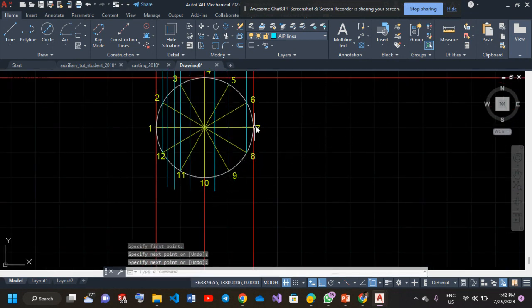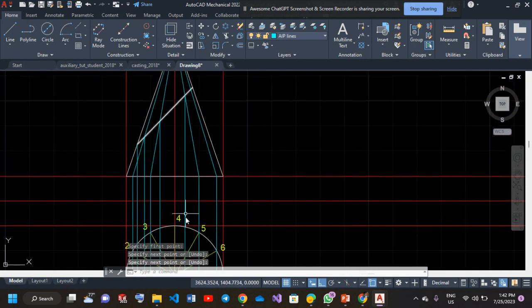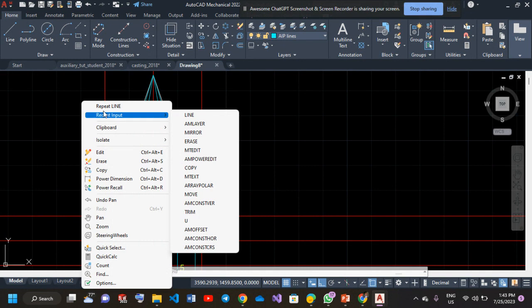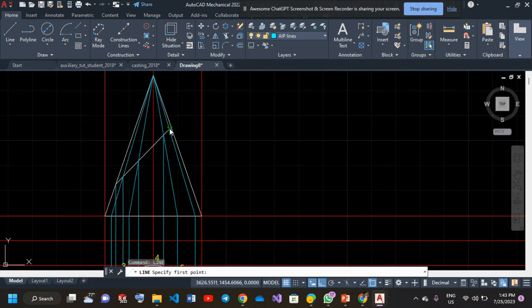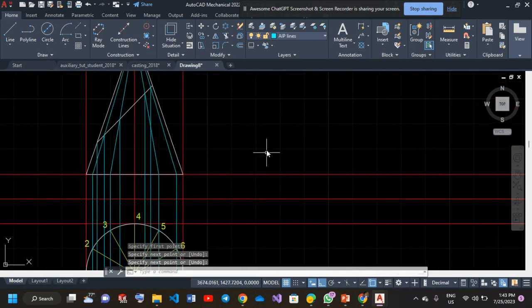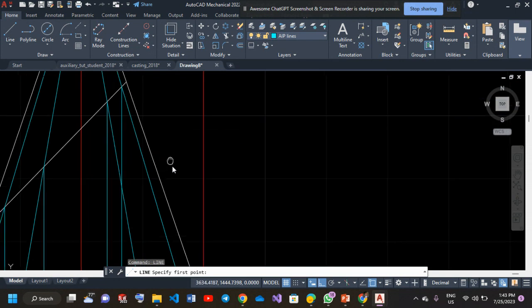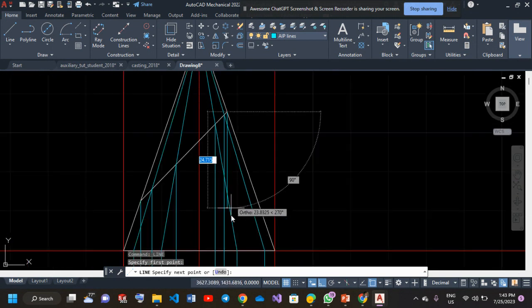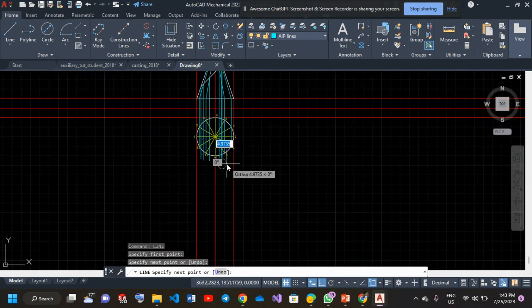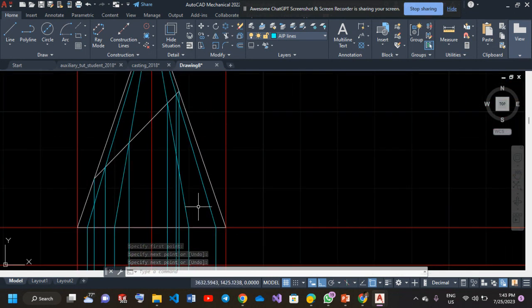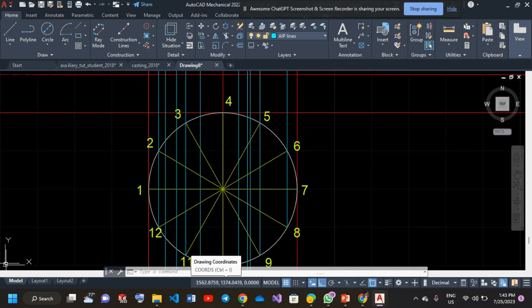Now, if you realize, the 4 and then 10 is starting from here, which is traveling the same path as the center line. So there's no need in doing that. Okay. So what I'll do is repeat the line, then do it for this corner here, downwards, and then repeat it again for this last point here. Okay. Then we project it down in that orientation. So basically we projected our lines down like that. We need to get the effect on the plan.